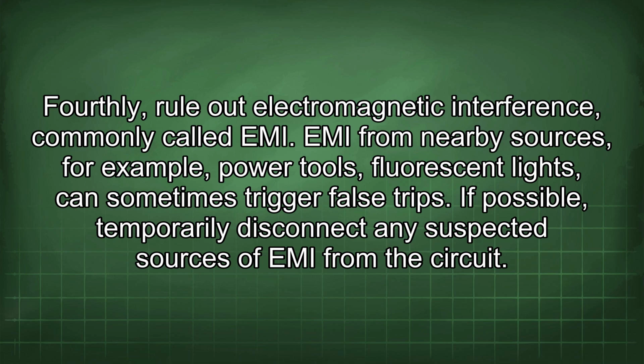Fourthly, rule out electromagnetic interference, commonly called EMI. EMI from nearby sources, for example, power tools and fluorescent lights, can sometimes trigger false trips. If possible, temporarily disconnect any suspected sources of EMI from the circuit.